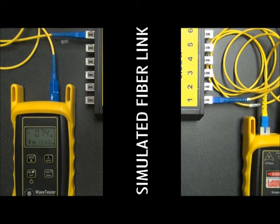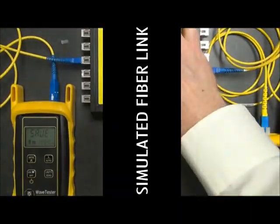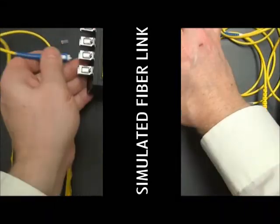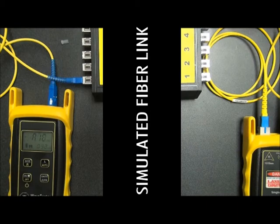I'm just going to speed up the process again and test all readings at 1550. And finally, save a reading for fiber number 6, again at 1550 this time. Now as you can see, the number 12 shows up there. So we stored 12 readings, 6 at 1310 and 6 at 1550. Once we've taken all our readings, we can take the WaveTester to a PC and download them into a certification report.